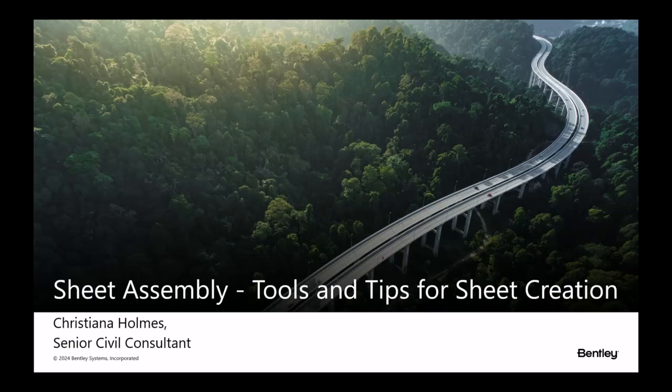So the tool for creating sheets and/or name boundaries, I should say, is the Place Name Boundary command. And so this dialog that you see creates the name boundaries, and you have a handful of different ways you can do that. The first 5 are civil, so you have 2 for plan, 1 for profile, and 2 for cross section. The last 3 are general MicroStation based types of sheets.